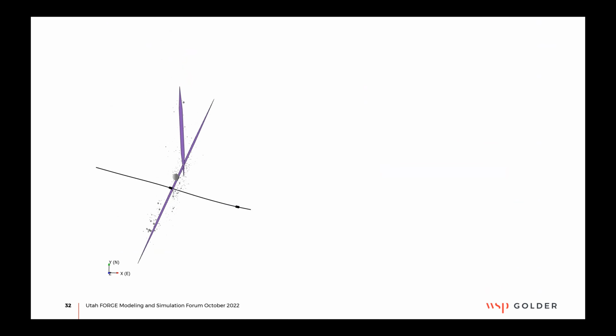And this is why I ask about length scale: if the fractures are small compared to the ultimate hydraulic fracture, then I imagine that a hydraulic fracture propagating through this sea of smaller natural fractures will seek out some kind of tortuous path that is determined by the present day stresses. And so I don't think there's necessarily a correlation between the paleo stresses and the present day stresses, in other words, a correlation between the natural fractures and the hydraulic fracture. So I wondered if you had some thoughts on that and whether you believe the paleo stresses are aligned in some way with the present day stresses.